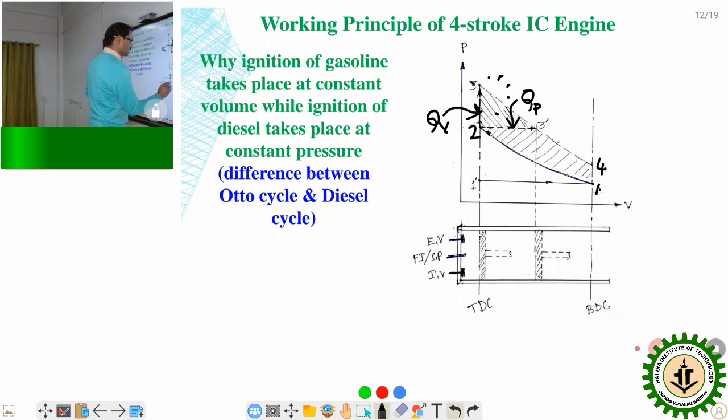So in case of diesel, diesel will be sprayed here by the nozzle at the end of the stroke. Air is at high temperature, compressed air with very high temperature. It will vary from 500 to 900 degrees centigrade.